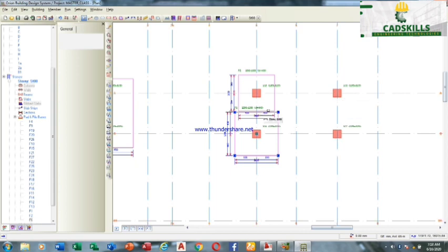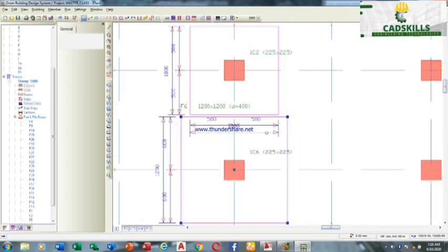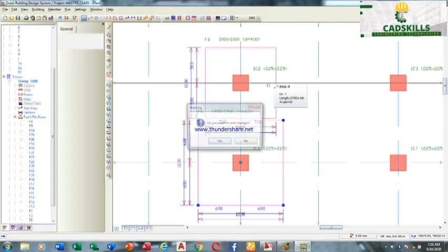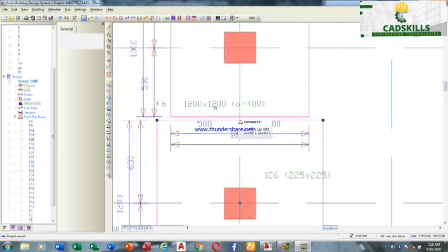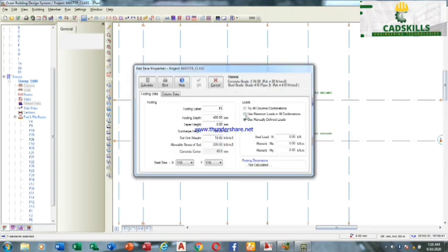Because if it overlaps, and I leave it like that and use this exactly the way it is on site, it means that this base and this base will clash. So the best thing, if two of them are overlapping, is to combine them, but you can see that we are still okay with what we have designed. So always consider economy in your design. It will help you.